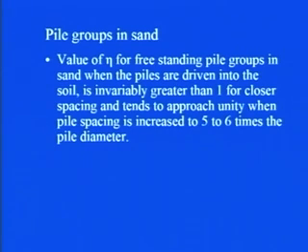So, I hope that you remember that we discussed two types of pile group, free standing and fixed standing, where the pile tops were related to each other with the help of a pile cap. Now, in the case of the freestanding pile group, you have seen that the pile cap was not in contact with the soil. So, in that case, for closer spacing, your eta value will be greater than 1.